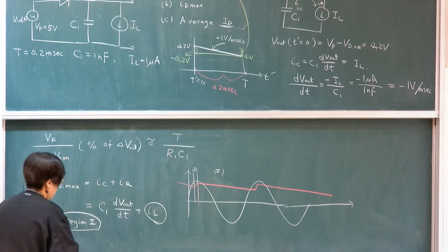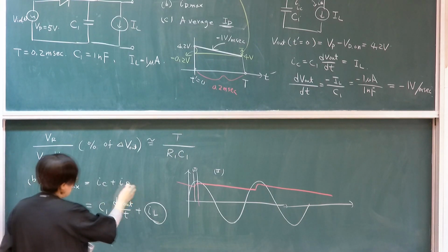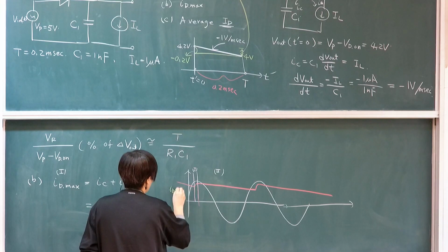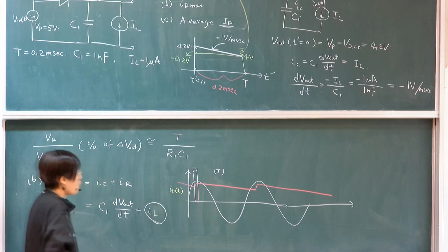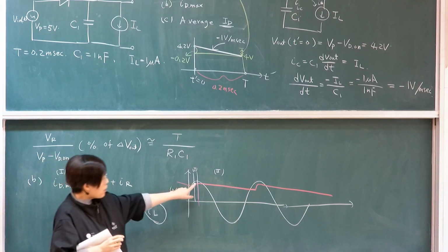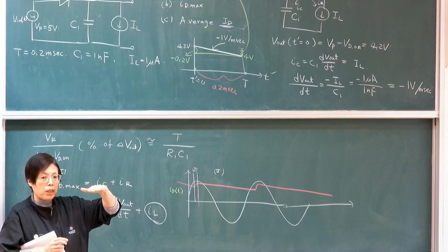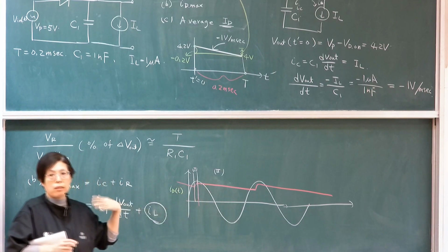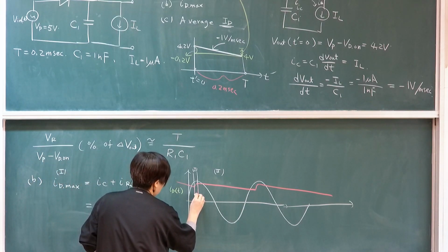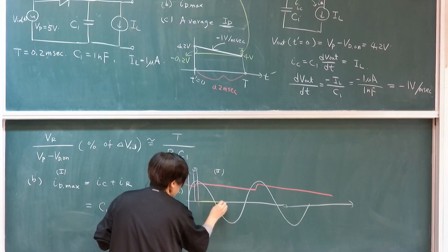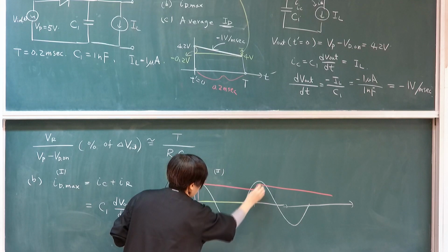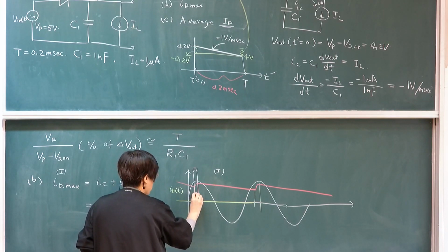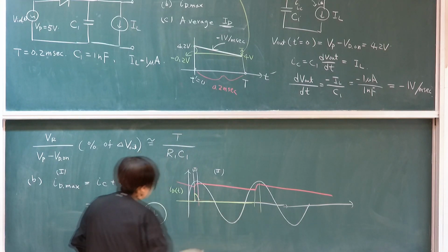During the on period, it's supposed to be 1, if I'm following that. If I'm drawing current, ID, as a function of time, it will look something like this because it depends on the ramp. So when it's flattened out, when you're reaching the peak level, there's no need of charging current. So at the peak of the sine, its derivative is 0. So you actually see something like this. When it's off, of course, it's 0. And then it will only start charging. It will jump up when it turns on, and then it will drop to low, and then drop.